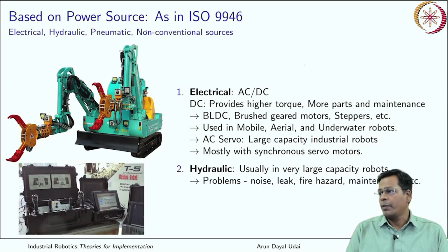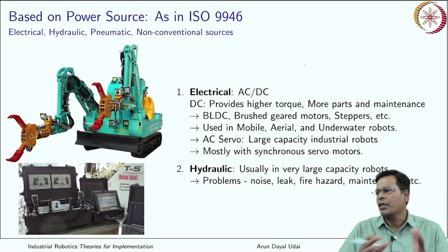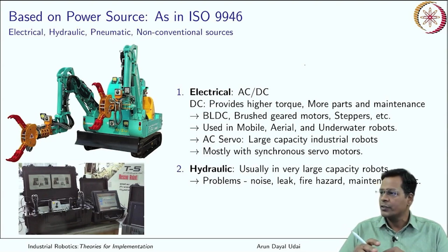But everything comes at a cost. Even this one, to generate hydraulic power, has to have a hydraulic power pack which keeps a motor running continuously, that keeps on developing the pressure for the actuators. So it creates a lot of noise, and it uses oil. Obviously there are some leaks which can happen, and because it is oil, there is a fire hazard.